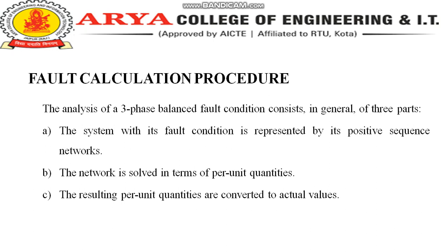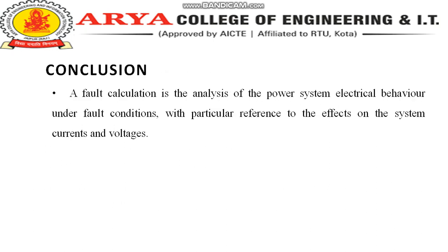The first one is its fault condition is represented by its positive sequence network. The second one is it is solved in terms of per unit quantities, and the third one is the per unit quantities are converted to the actual values.